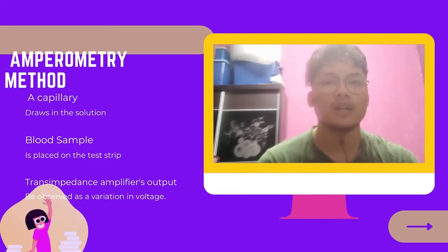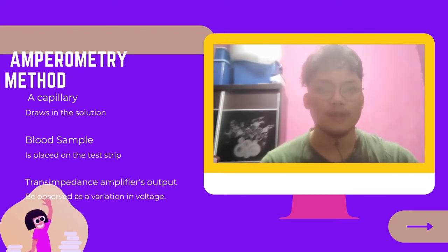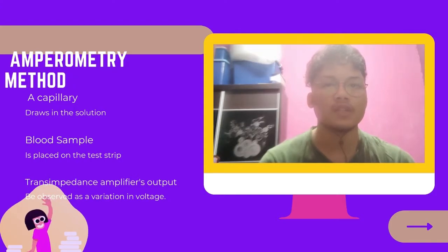So, in order to adjust for the effect of temperature on the pace of the reaction, an ambient temperature measurement is also taken. And when the blood sample is placed on the strip, the glucose is reacted with the enzyme. Okay, the current flowing through the working and reference electrode will correlate to the flow of electrons. And depending on the glucose level, this current will alter.